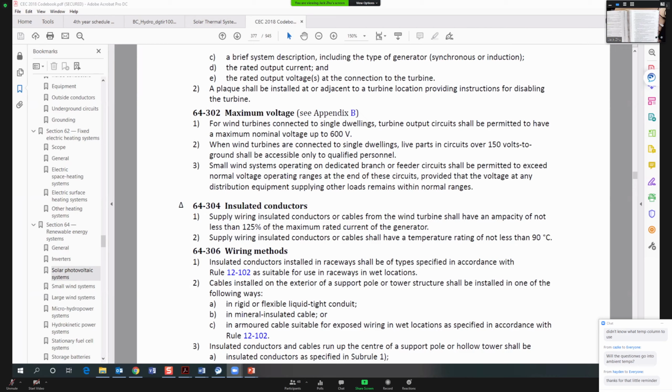So if the equipment is rated for it, because we need 90 amps, if there is no requirement, we can go with number 4. If we say the temperature rating is 75, then you'll have to go to the next size larger.